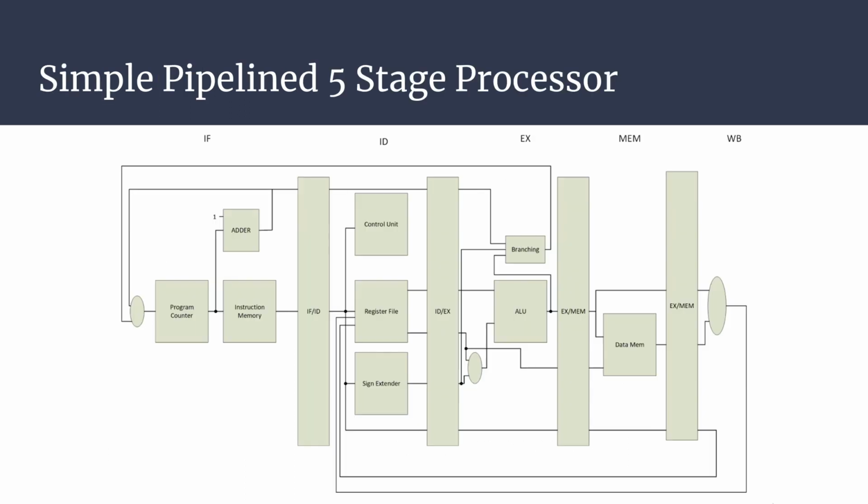So this is a simple 5-stage processor that we implemented the RISC-V 32i ISA on. Notice that there isn't a hazard detection unit or a forwarding unit. This is because we plan to use a 4-way multi-threading later on. So by the time that one thread is in the write-back stage, that thread won't occur again until the data has been written back to the register file. So we won't have any data hazards.